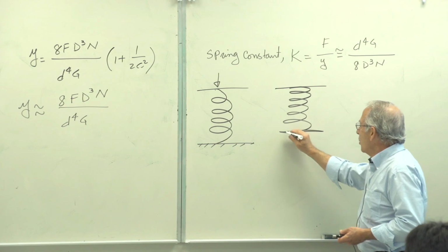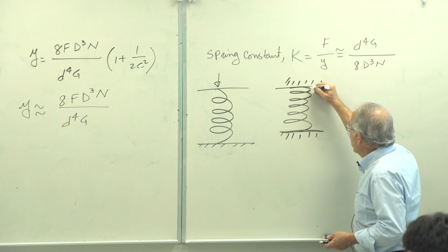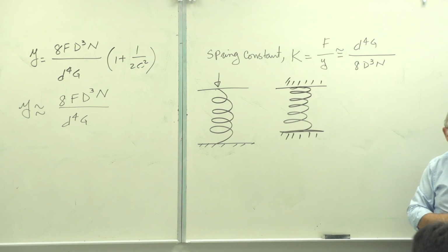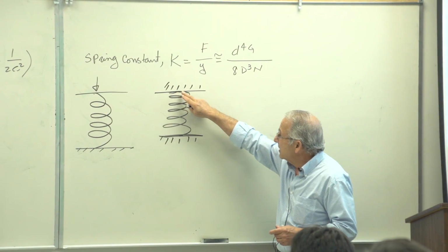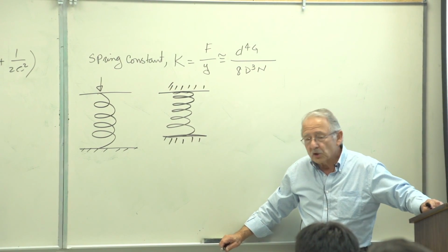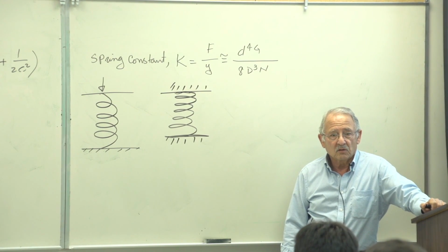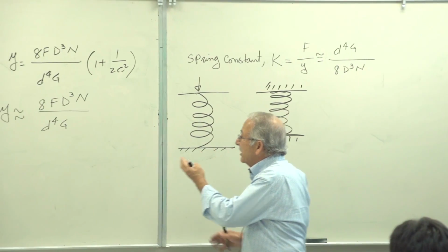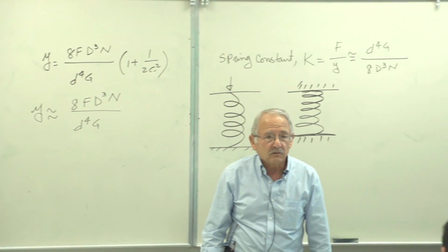So I may have a whole coil, in fact, in this case I will, may have a whole coil flat against that flat plate. The part that sits against these flat plates carries no torque and no shear load. Therefore, no strain energy is there. It stores no strain energy, therefore it can't be a part of this equation.